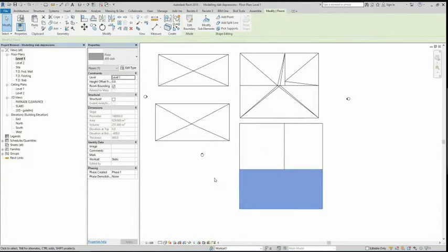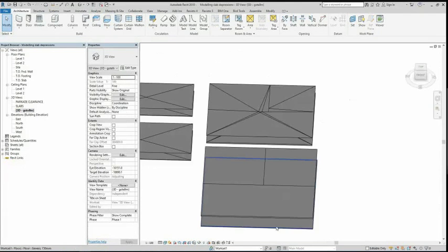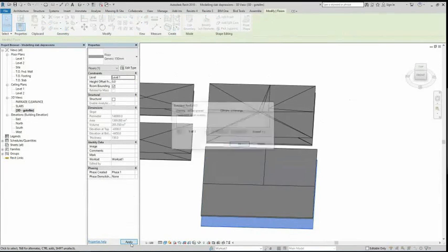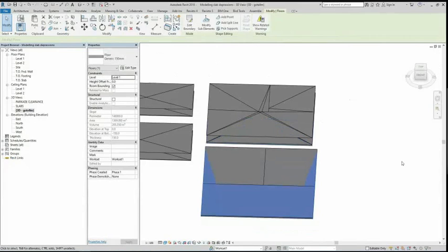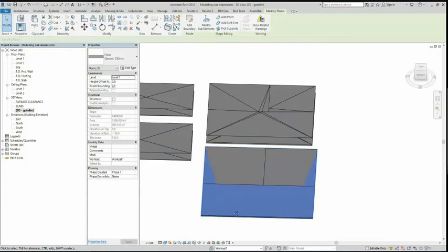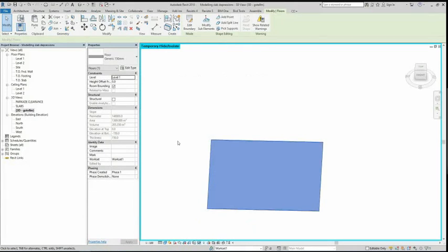All right, I want to make sure that it is at the correct elevation again, and it's not. So I'm going to switch it back to level 1. And it's telling me that the floors overlap, which is fine. So I'm going to select that one single sacrificial floor element. And what I want to do is isolate the visibility on that one specifically. I'm just trying to find the isolation view. Because I have it highlighted, I just go isolate element, and that's all I can see.